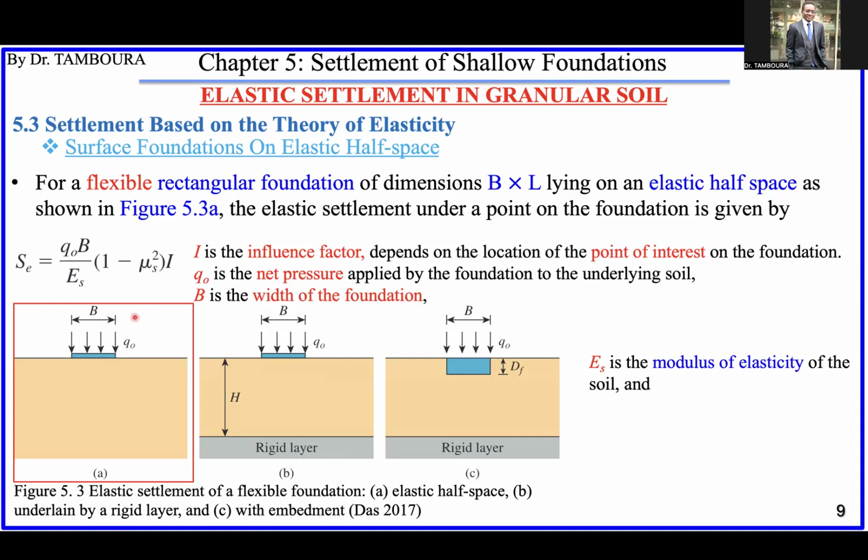And what is Es, the modulus of elasticity? Okay, that can be obtained also from the site investigation, or lab tests. In the site investigation phase, you can obtain soil parameters. Okay, chapter number 2, which we show in this program. Yeah, and next we can obtain also easily the Poisson ratio. Sometimes you can just assume it 0.3 or something around that. Okay, so as you can see, all these parameters can be obtained easily except this I. Okay, so what is this I?